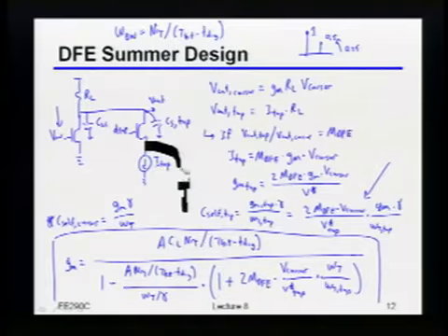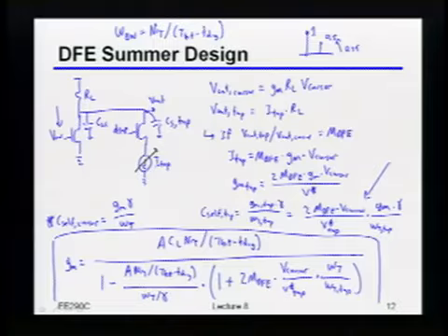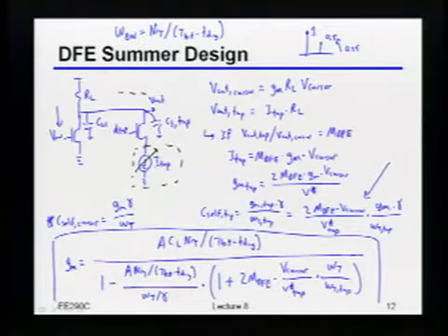And by the way, for reasons that we'll talk about in more detail later on, this is obviously a digitally controlled thing, and let's say it's about a 6 or 7-bit DAC. There might actually be a lot of parasitic cap on that node. In fact, you may even want to pull this thing so that physically in the layout, it's sitting halfway across the chip, just so it's not screwing up your nice, clean, high-speed signal path, where you want as small a parasitic cap as you can get.